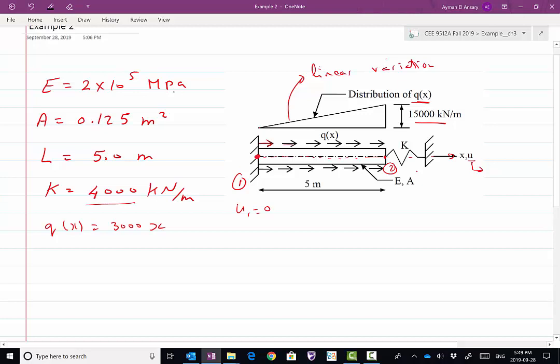As we discussed in video number 1, in SAP2000 there is no bar element, so we used a 3D frame element which has 6 degrees of freedom per node, and we reduced this high order element by deactivating all degrees of freedom except the translation along x. So we reduced it from a 3D frame element to a one-dimensional element to simulate the bar. This means that we are using a high order element to simulate a very simple problem. So in SAP for this problem I'm going to model the entire bar using one element only, which is element 1 connecting node 1 and node 2.